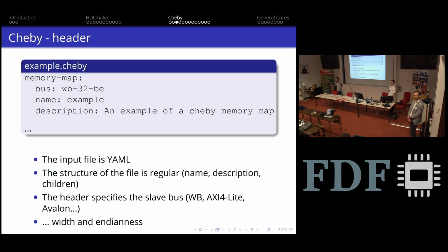Sorry, I just have a question regarding the White Rabbit project. Probably this has no direct relationship, but you have shown a lot of cores, a lot of building blocks. With White Rabbit, part of the synchronization can be done, but I know there are some hardware specifics you also have to do on the board. I know that you can use gigabit transceivers to do that. How do you handle, for example, the big jump between Series 7 and UltraScale in the gigabit transceivers, which are specific to the vendor?